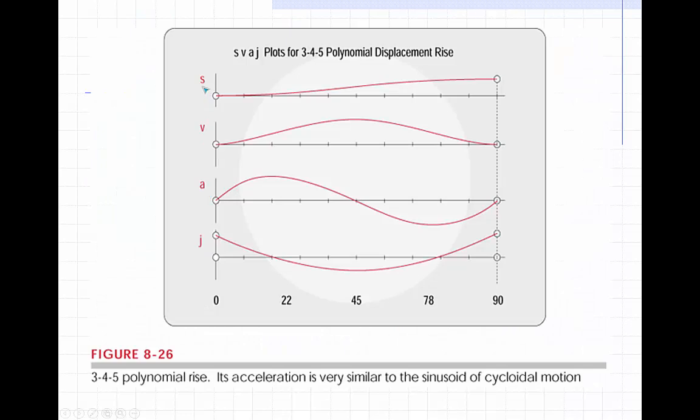We see that it's a nice looking curve for the rise, for the velocity, acceleration, and jerk. We are continuous through the first and second derivatives, and the corollary to our fundamental law, our jerk is finite. And so this is a good result for our CAM design. The fall would have a similar looking set of equations. We won't focus on the fall for this particular case.